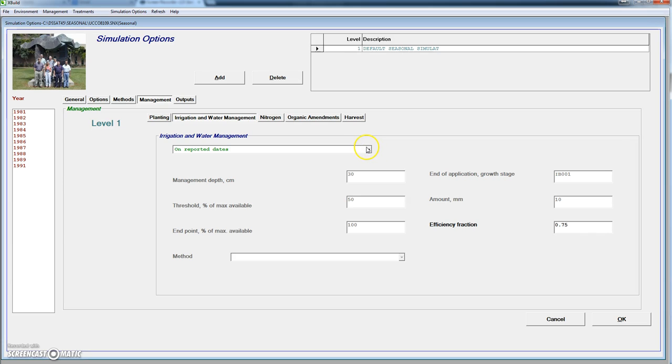To avoid including an actual irrigation schedule, we're gonna use automatic irrigation when required. For a maize crop, we may consider a 100 centimeter depth for calculating irrigation, and it will apply irrigation every time we cross the 50% of available water, and then irrigations will be applied.